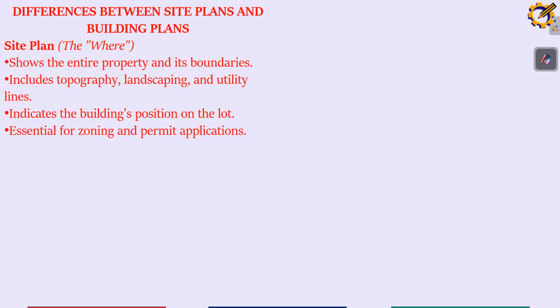Now imagine you are purchasing a land very close to the airport, right at the airport gate. Now you design maybe a high-rise building, like a 20-story or 30-story building, and you take it there. Without the site plan, they would approve the building plan, because the building met specification and everything. But with the site plan, they will be aware that this area is closer to the airport, so they can't permit a high-rise structure closer to the airport. So they will disapprove that building, and it is good for you to be aware of that before erecting the structure.